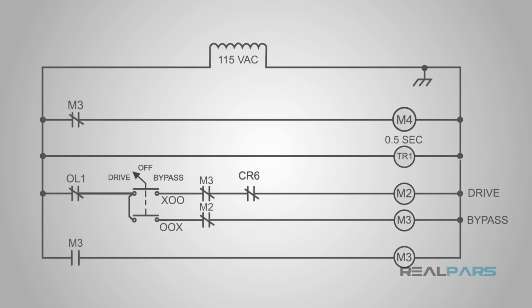Since the real world is more complicated than just on and off, we need some more complicated functions to deal with it. One of these was in the original drawing I started this off with, and I wanted to come back and cover it. One of the most common functions, other than on and off, is a time delay, something that waits a specified period of time before turning on or off. We have had one in this drawing, although its output isn't specified. We call these timing relays when we use them in a circuit like this drawing.